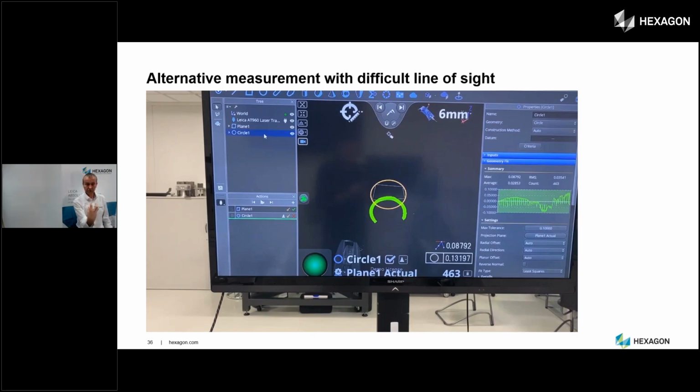Now, basically, you can adjust the movable, the flexible end of the roller to this circle. Just the Y coordinate will change. So that's basically the idea. We measure a reference circle on the fixed end, and now we adjust the other end to the same circular position.